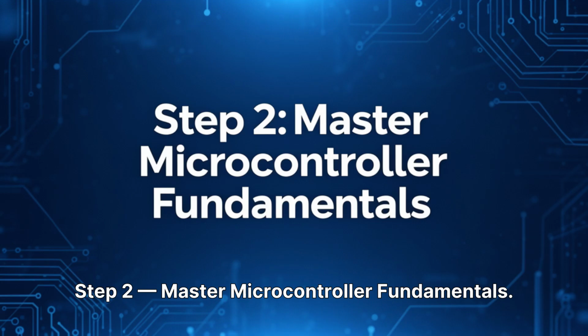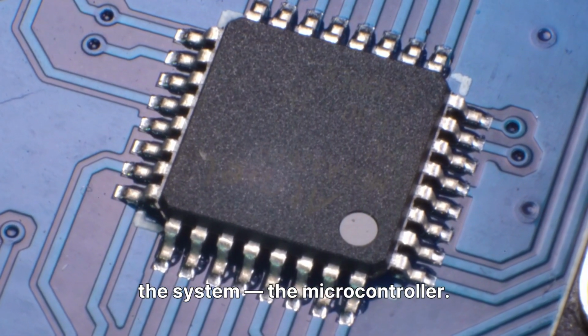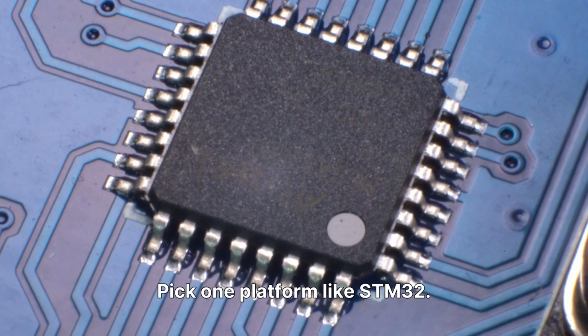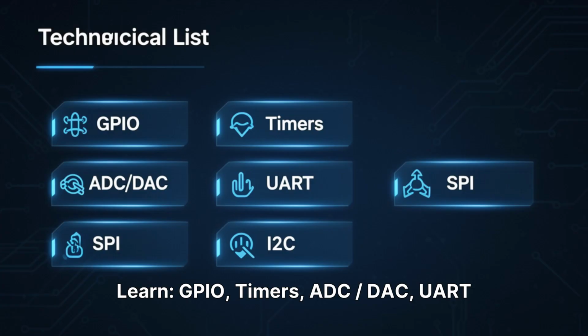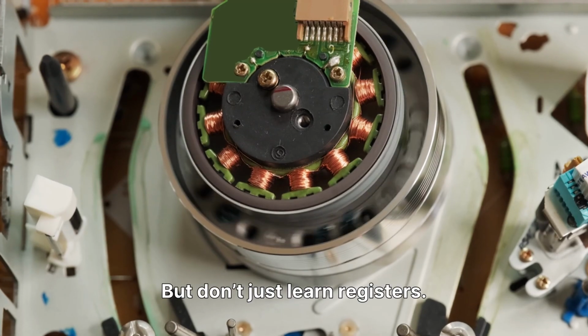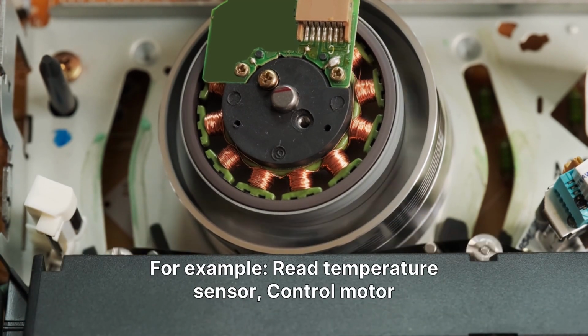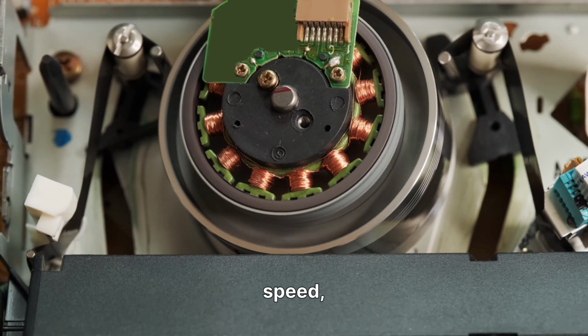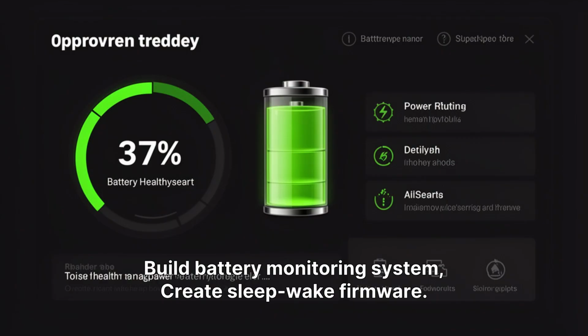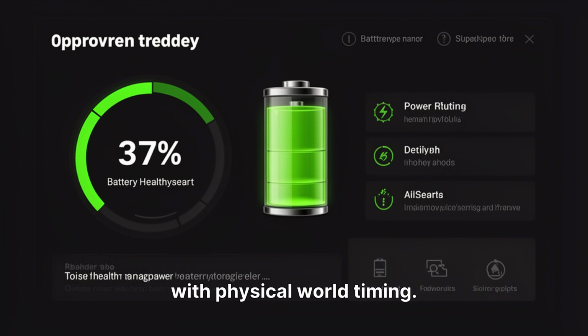Step 2. Master microcontroller fundamentals. Now you move to the brain of the system, the microcontroller. Pick one platform like STM32 and go deep. Learn GPIO, timers, ADC, DAC, UART, SPI, I2C, interrupts, low power modes. But don't just learn registers. Build small real-life use cases. For example, read temperature sensor, control motor speed. Build battery monitoring system, create sleep-wake firmware. This builds intuition about how firmware interacts with physical world timing.